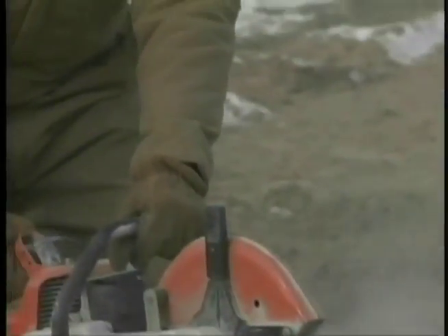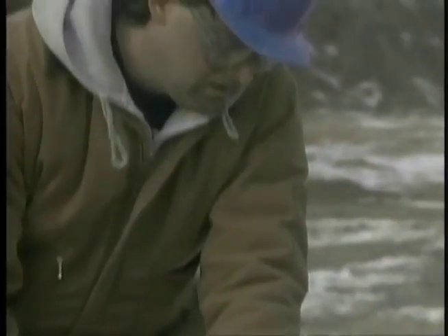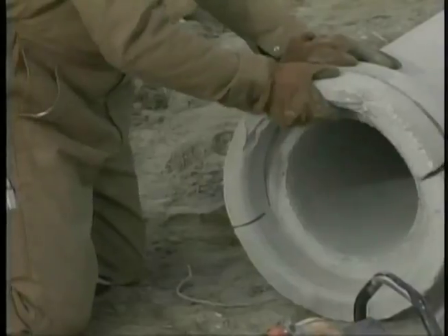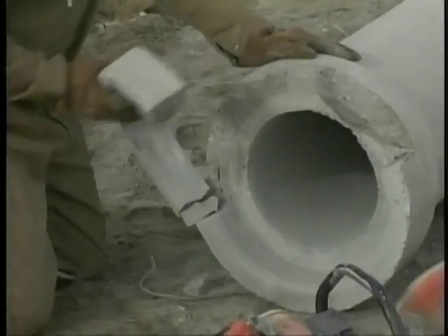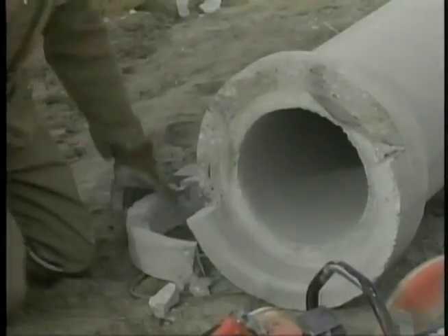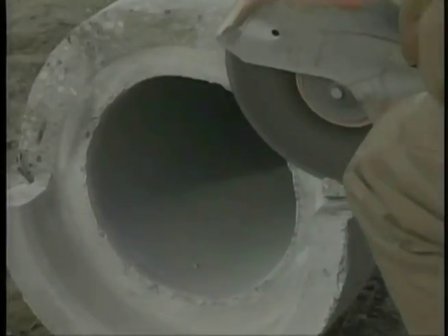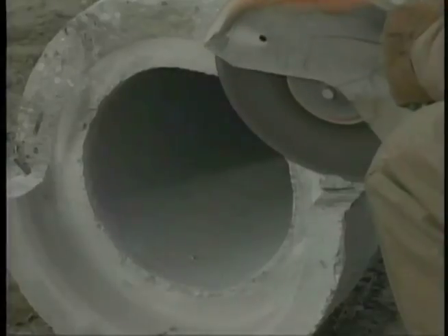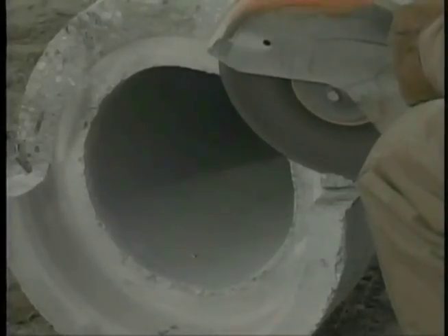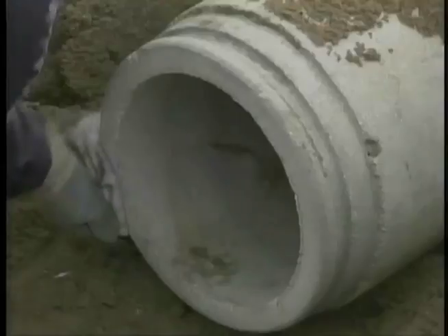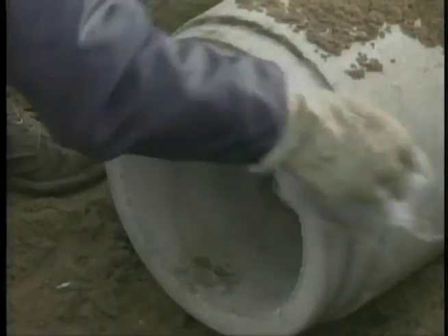When sawing any type of pipe, pay attention to any material being discharged from the saw blade. Remove half the bell on the replacement pipe. Trim the cut. Follow the same steps for cutting the existing pipe. Take care not to damage the bell or spigot end of the existing pipe. Dig bell holes, clean and prepare the spigot ends of both pipes.